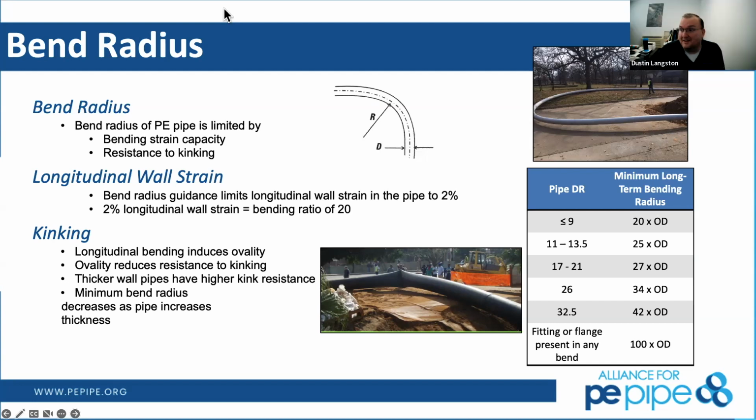That was for me or for Alan? No, you guys decide. Oh, sweet. Go ahead, Dusty. Absolutely. So I get this question all the time. Hey, had a contractor, we pre-chlorinated a drill string, and we came back a month later and we forgot to drain it. So it's had chlorine in it for a month now, out in the Florida temperatures, high temperatures. Is that okay? Has it done any damage? And the answer is ultimately no.